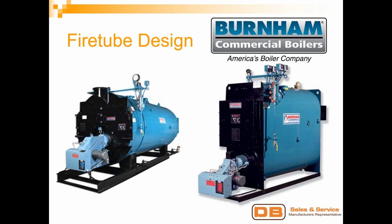First up, we talk about one of the traditional workhorses of the boiler industry, the Firetube boiler. That was rocket science when they decided to call this a Firetube boiler. We represent the Burnham brand of Firetube boilers. They make a traditional Scotch Marine type boiler, which has a completely water-cooled furnace, and they do these in low pressure steam, high pressure steam, hot water, and other applications as well.